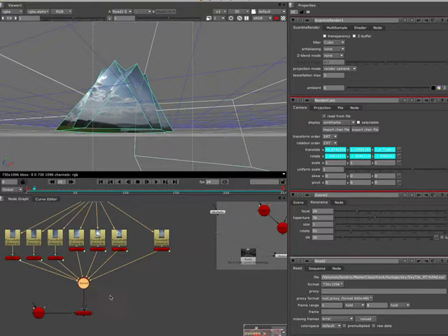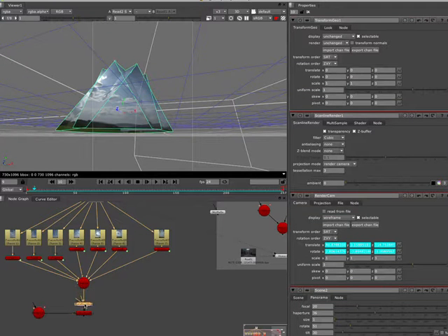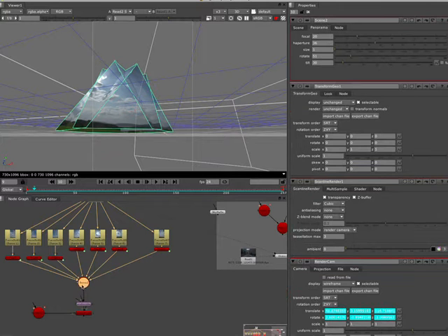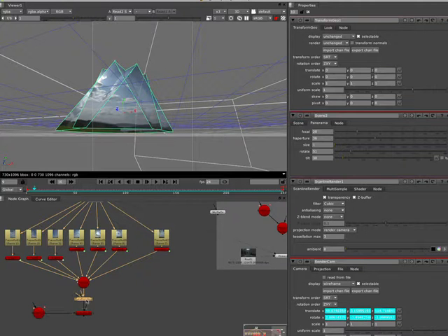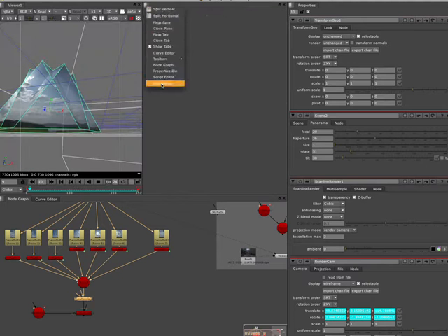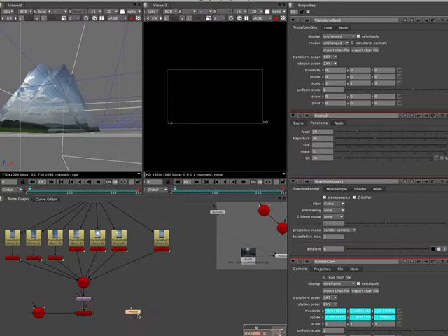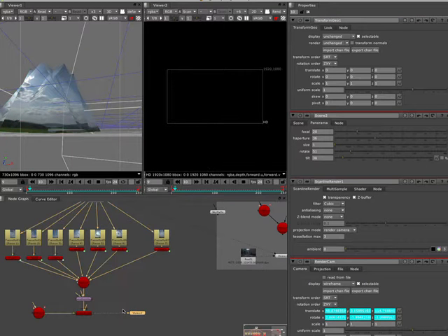And the other thing I might do is I might just chuck a transform geo in there. I could do this within the scene node itself. This is our panorama scene node. I can rotate and do all this stuff here, but I'm just going to do it with the transform geo because it's a little bit easier. I want that, not that. Cool. So the first thing I'm going to do is split my viewer into 2 and make a new viewer. And I'm going to connect that up to what I'm looking at over here. And I might look at the output of my scanline render node, right?